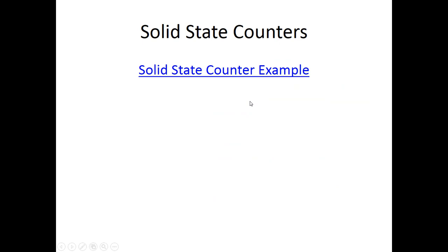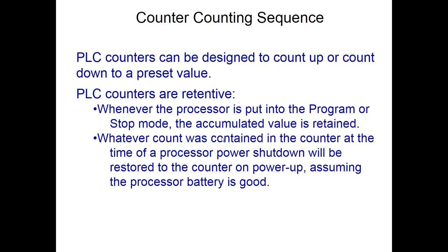Here's your solid state counter example to see what's going on with the solid state devices. And now remember, these items here require resets. So you're going to click this, and you'll see that the solid state devices act as retentive, and there's a separate reset button in them. So PLC counters can count up or down, okay, and they're retentive.